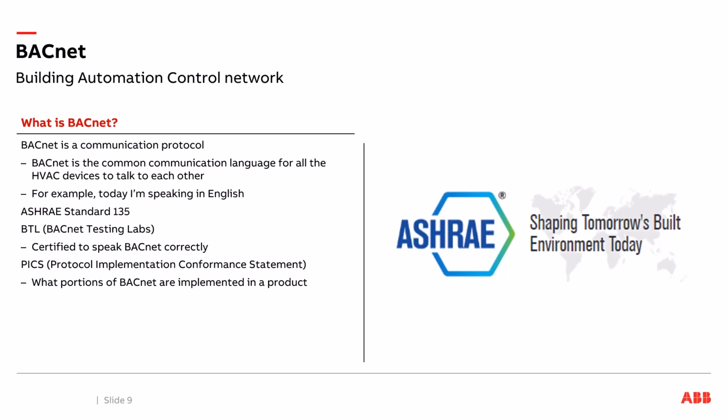So the industry said, you know what, that's not acceptable. It doesn't matter if it's an ABB drive, I'll use drives as an example, Danfoss, Yaskawa, Eaton, Delta, pick any of the 15 drive manufacturers. Shouldn't matter what drive it is, shouldn't matter what controls person it is, whether it's Honeywell, Johnson Controls, ALC, Allerton, Cylon, any of those manufacturers, they should be able to talk to each other also. So what they did is they came up with BACnet, which allows that common language for all these different devices to talk to each other. And BACnet sets that standard for how that protocol works.